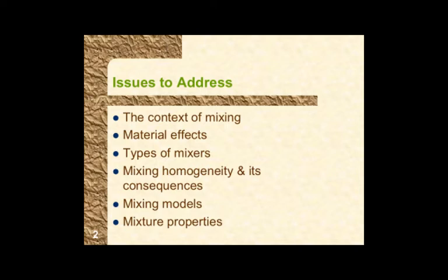We looked at rheology on one hand, but it can be thermal conductivity, it can be heat capacity, right? We need to know what those properties are and how to predict that as well with these models so that you can control the process. If I mixed A and B and got a mixture, and okay, I got it homogeneous, can I make a shape with it, with this process, is the question. And so whether the answer is yes or no depends upon what are the properties. If it doesn't flow well, then it's not a suitable mixture and you got to create another mixture, right?